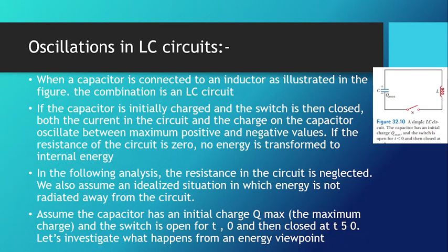It's quite logical to expect that there will be a huge current flow at the beginning and then the current flow will reduce. However, this will not happen in practice. An inductor develops EMF across it based on the change in the current flow. This means that a drastic change in the current is not possible across the inductor. Now the current flow starts from zero and increases to the maximum and then comes down to zero again.